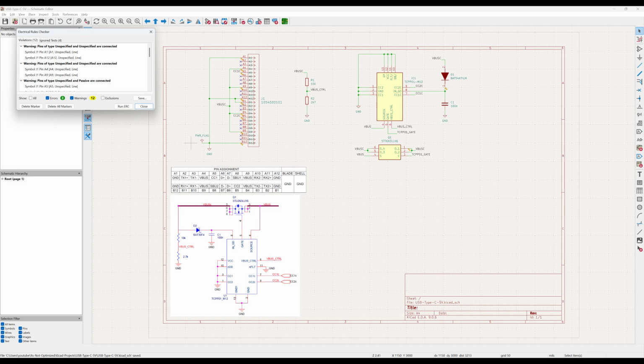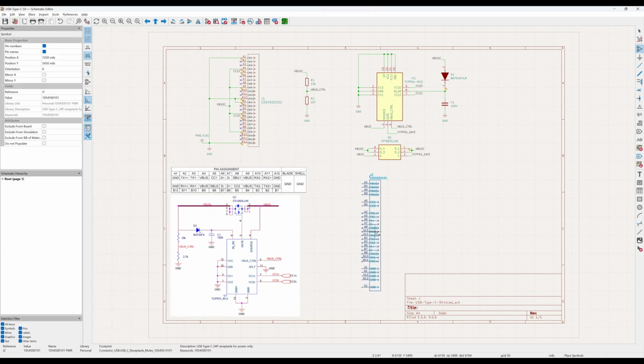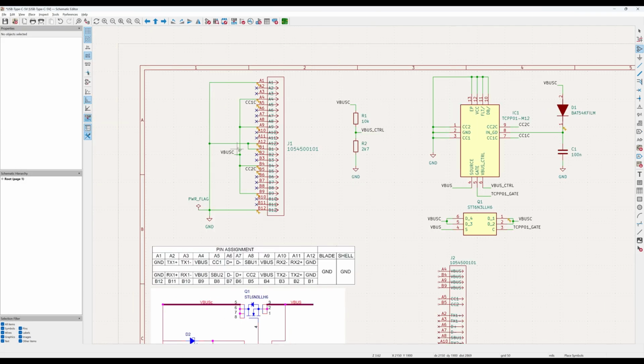This brings us to the third reason we could not move on to PCB layout. Our schematic is a bit ugly and difficult to understand. The symbols have a large effect on the ugliness and understandability of the schematic because they force the connections to be made in a particular way. Additionally, as we see here, a symbol can also create ERC warnings when the pin types are not correctly defined. Let's add a customized version of J1 into the schematic and connect it.